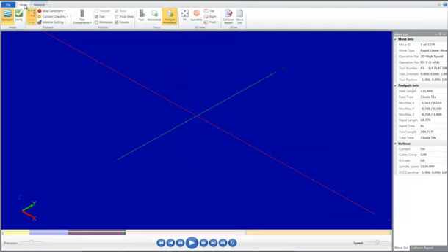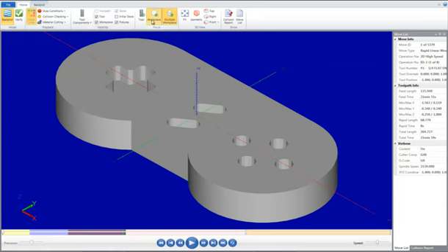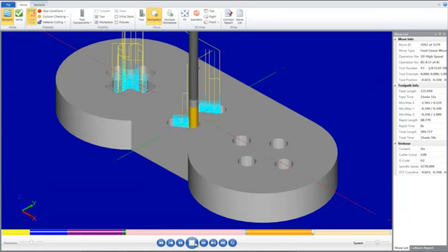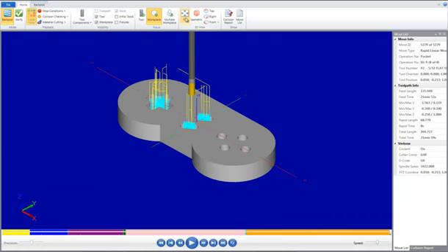You can now select the Home tab. From here, ensure that Tool, Workpiece, and Workpiece are enabled. Disable fixtures if necessary. You can now press the Play Simulation button to run your backplot. Your toolpath will appear as shown. To view your part more clearly, select the Isometric View and Fit icon.